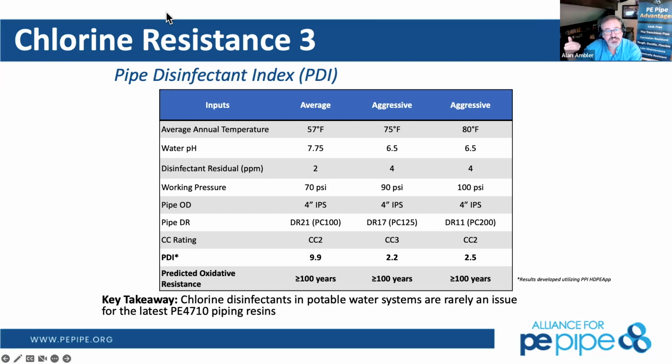Chloramines are a lower disinfectant. They are put in as a secondary disinfectant in the pipe networks. There is some material out there that shows they can be aggressive to gaskets in a bell and spigot gasketed system. Liquid chlorine is the next one up. Remember, chlorine dioxide or chlorine as a gas, which used to be used and is not used much anymore, are very aggressive oxidizers that are potentially very dangerous as well. So at the treatment plant, they have to handle them, and that's what they're intended to do.